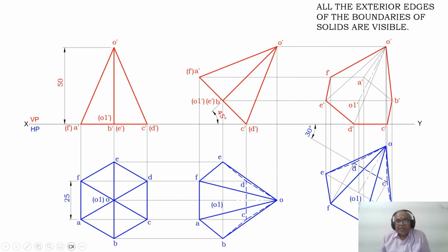Similarly, using the protractor from the point D with reference to DC, you measure an angle of 90 degrees below this line and draw a perpendicular line from D, and similarly from C also. Then you measure the distance from D to F, which is the same as C to A, and transfer it from D onto that perpendicular line, similarly from the point C also. And you mark these two points, A and F. Similarly, you measure the distance from C to this point or from D to this point. Both will have equal distances.